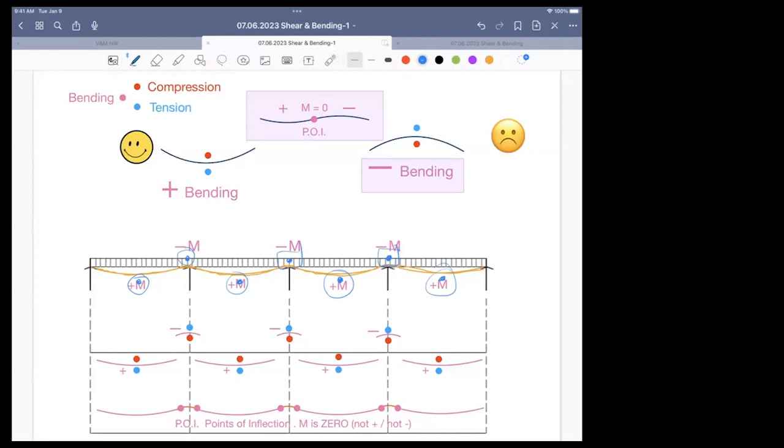It is extremely important to understand this diagram. And it has nothing to do with the moment diagram. We understand deflection very well. We panic with a shear moment diagram and numbers, but we understand the deflected shape. So if you have positive bending, your tension is on the bottom. If you have negative bending, your tension is on the top. And I need to follow up with my rebar, wherever that blue dot is.